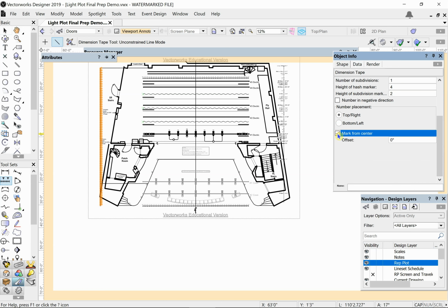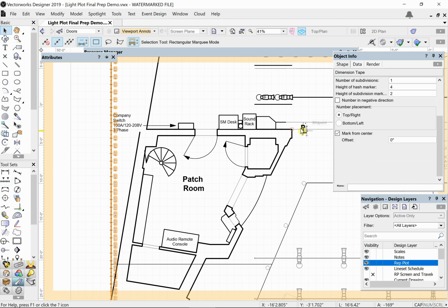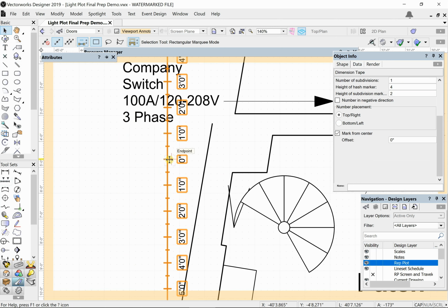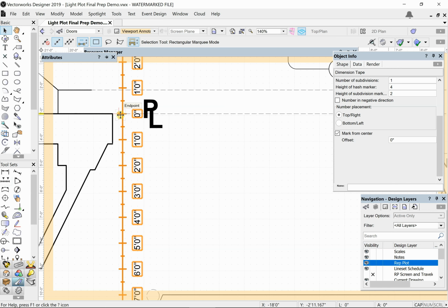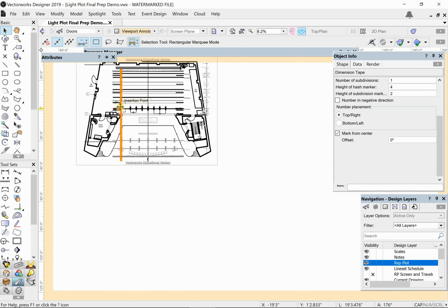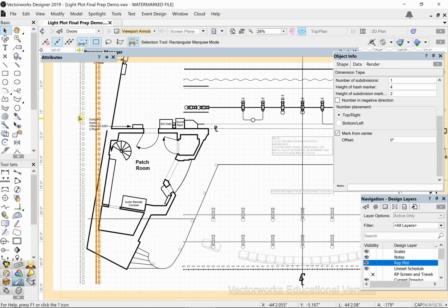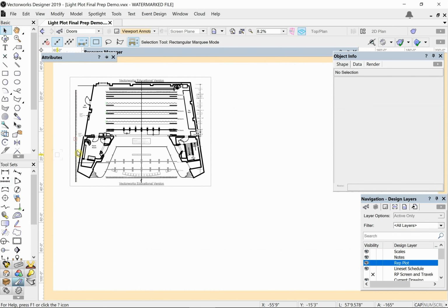And it's nice to mark from center here too, but in this case, the 0 point wants to go on the plaster line. That's this little dashed line here marked with the PL. So I'm going to find my 0 mark. There it is. I'm just going to drag it over and snap it to the plaster line. And then holding shift, I'll drag it back perfectly horizontally until it's somewhere usable, not obstructed by anything else, like that, right? So that's that, and then I could duplicate it and put it on the other side too.